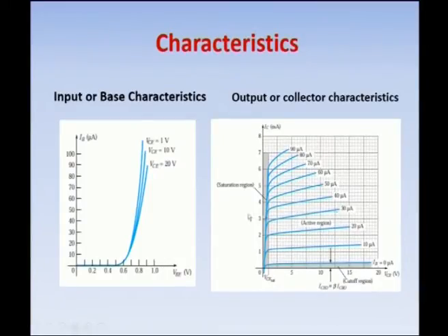This is the input output characteristics. We know that the input characteristics is drawn for the input parameters. The input current is IB for the common emitter and input voltage is base emitter voltage, for the output voltage constant. Collector emitter voltage is constant. Here for the collector or the output characteristics, it is drawn for the output parameters with the input parameter constant, output current along the y axis and output voltage along the x axis, VCE, that is collector emitter voltage, for the fixed IB current.